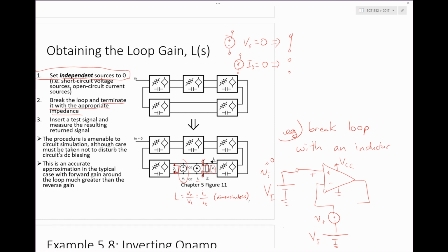So instead, one approach to doing this is to say, okay, this is all just an artifact of you trying to break the loop. Because when you connect this in the real world, or in its actual use case, you've got closed loop. And in fact, the feedback takes care of the offset itself. The negative feedback establishes the exact voltage that's required at the negative op-amp terminal, assuming the loop's stable. It's going to establish the exact right voltage there so that the output is at a nominal operating point and everything's good.